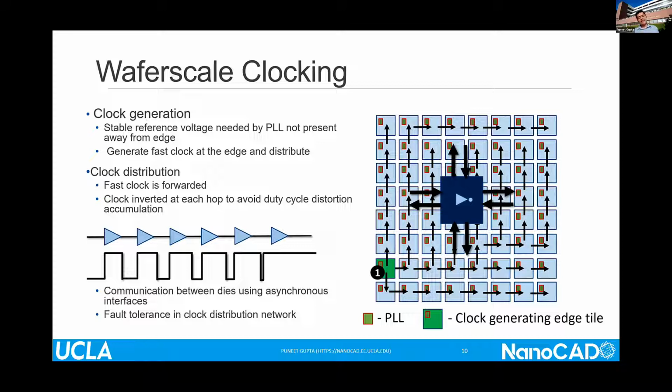One more thing that we did, to account for some chiplets failing for whatever reason, is build fault tolerance into the clock distribution network itself. Every chiplet can source its clock from any of its 4 neighbors, depending on which one is active. It automatically detects which clock is still functional, uses that internally and forwards it further, just to have fault tolerance in the clock. Because if the clock dies, the whole system dies. So you have to ensure clock and power absolutely reach everywhere.